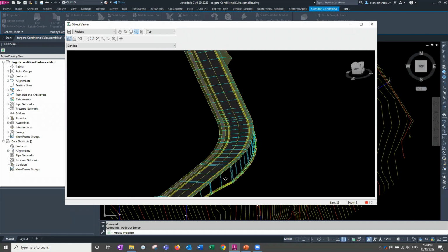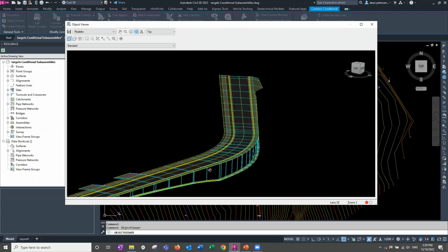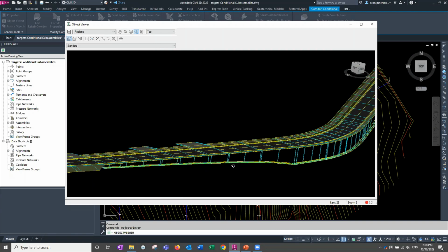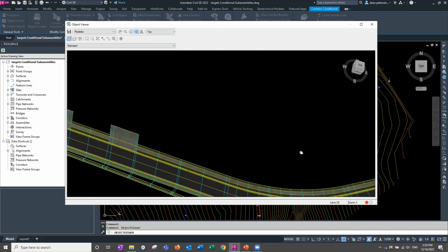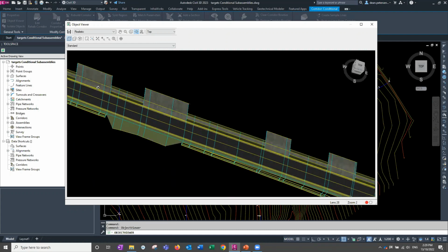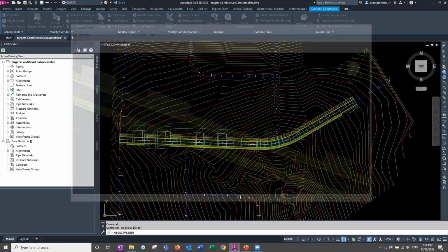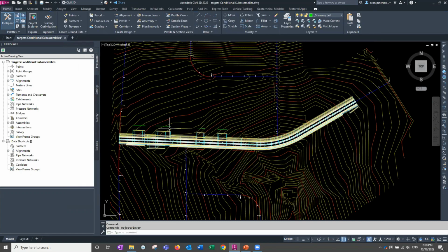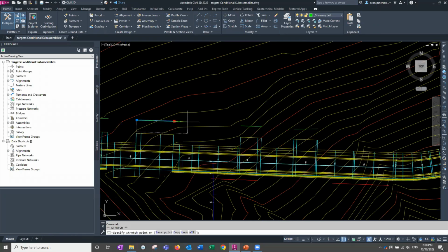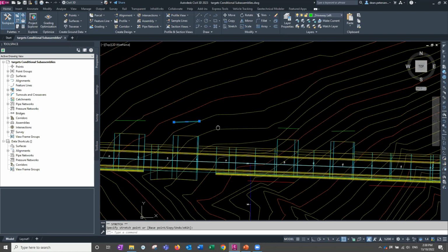For those who've done an advanced training with me, you'll know how this works. We do this as an exercise in the advanced training. What it's also got is some little stubs for driveways being added in wherever there are these polylines being added to the drawing on a particular layer. It means that you can pick those polylines and stretch them longer or shorter. The corridors are on rebuild automatic, and so it just makes those stubs longer and shorter dynamically.